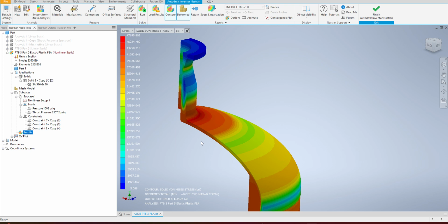But once the solution is converged, we check for the three convergences: work, displacement, and load. If everything converges 100% at every point, then we can say our component is stable under the given working condition, and it is passing the criteria of the elastic plastic stress analysis method. So the post processing part is very easy if we go for the elastic plastic stress analysis method.